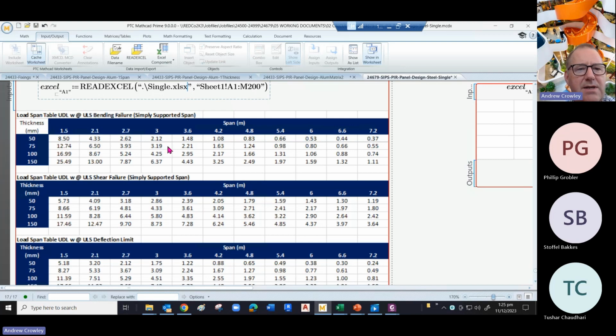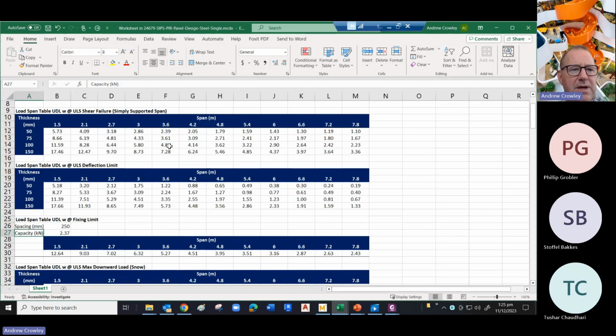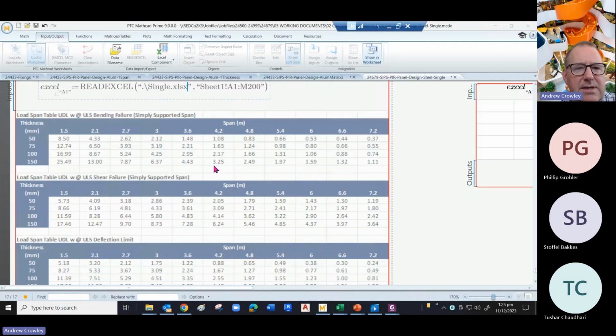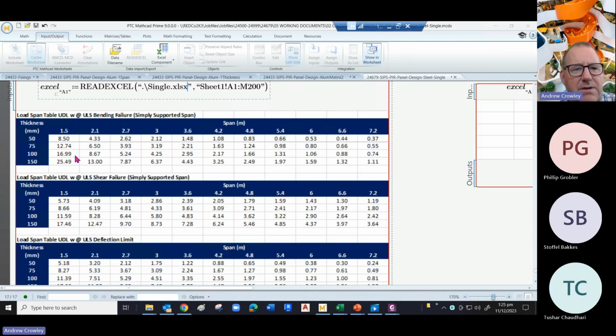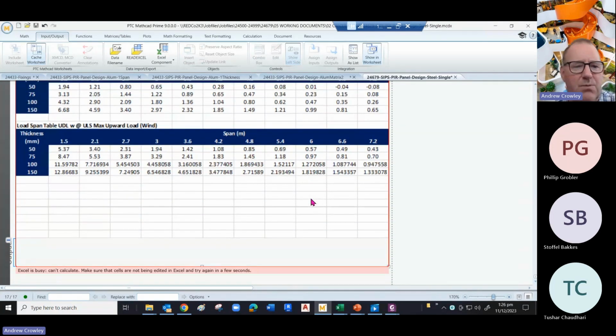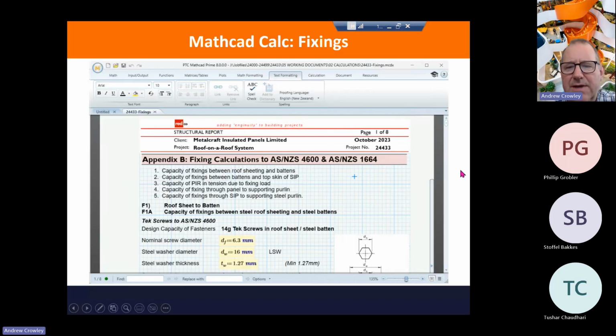And we can edit it like an Excel sheet. If you double click on it, it opens up Excel. Let's make that a bit bigger. And you can format it like an Excel. So you see that one, you want it to be formatted like so. Then you can update your Excel and it should update it in here. You can also resize the column so it fits onto your page. And that is how you get your Excel into your Mathcad. And once you've got it in, you can start manipulating it. So that was the last of the Mathcad.